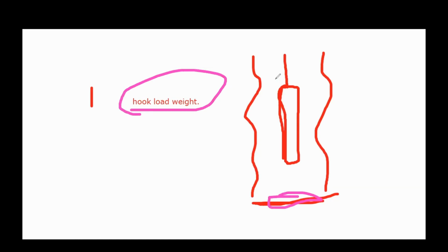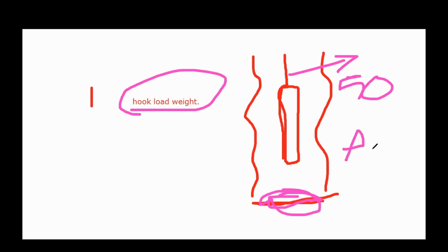Drastically changed means, assume this tool weight is around 50 kgs. When it touches the bottom of your wellbore, it will change, maybe to 40 kgs. So nearly 10 kgs of weight was changed due to hitting the bottom of your wellbore. There is a change in your hook load. At that time, they'll say they reached the bottom or the tool is stuck at the bottom.